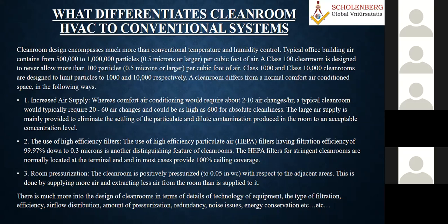Every federal government, every place, they have this, even for pressure gauges. I don't know how you people recommend any pressure gauge at the site when they are installing it in your chilled water pipeline, or even your chiller, high pressure, low pressure cutouts and all the things. So these pressure gauges definitely need a proper calibration certificate from time to time.